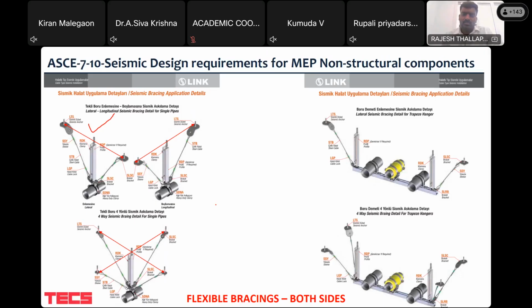So where you can see this is two-way restraint, means both sides it has to be restrained. Mostly the tension members are designed to have both sides, because tension members are nothing but solids. So if you take a solid rod, I'm not talking about the hollow ones, it's a solid one. If it is 100% solid, mostly they are tension members, but still we limit to certain shapes of the profiles. So always the tension member should be on both the sides, because it cannot take compression. It's just like a spring.